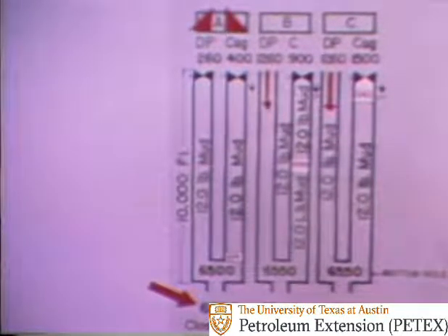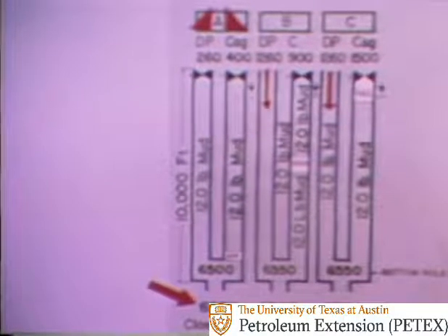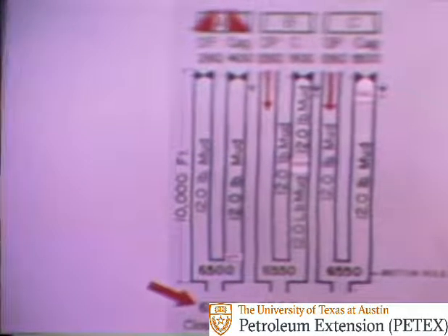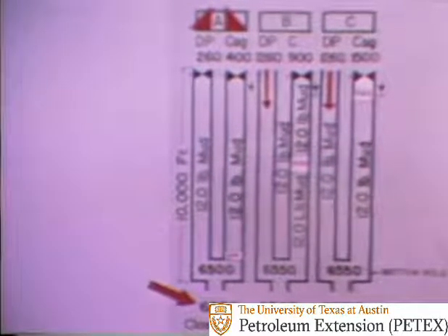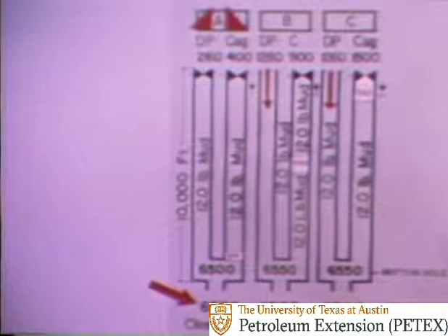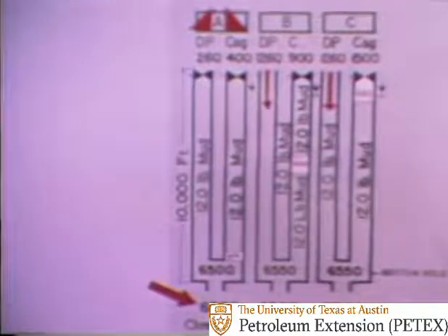Drill pipe pressure plus the hydrostatic head developed by the 10,000-foot column of mud in the drill pipe equals 6,500 psi, the formation pressure. The height of the intruded fluid in the annulus can be calculated, provided the pit volume gain was recorded, and the hole size is equal to bit size.